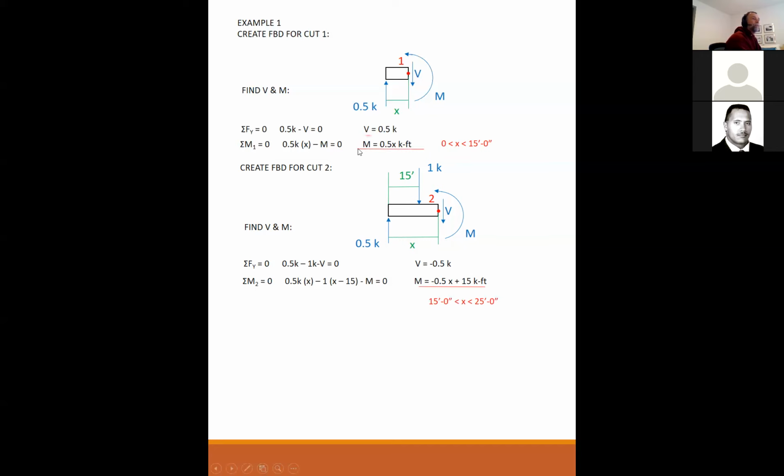So here's what you're looking for. This is the equation from 0 to 15. This is your equation from 15 to 30. This looks pretty simple, and it is pretty simple, but this gets kind of messy as we get down the line. So it is essential that when you get these equations for your moments, you simplify them into their simplest form possible, because we're going to be multiplying them together. Any questions so far?